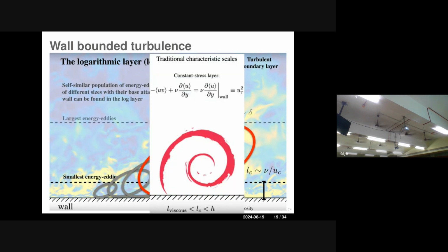Usually, what happens in this kind of wall-bounded domain, between the small and large scales, is that a kind of similarity happens. Your entire stress remains constant. This is the hypothesis. When that hypothesis holds, whatever the wall gradient is near here will be equivalent to the gradients that develop because of turbulent structures from the mean, and also turbulent fluctuations. So this remains constant, so that one can construct scale-wise arguments.